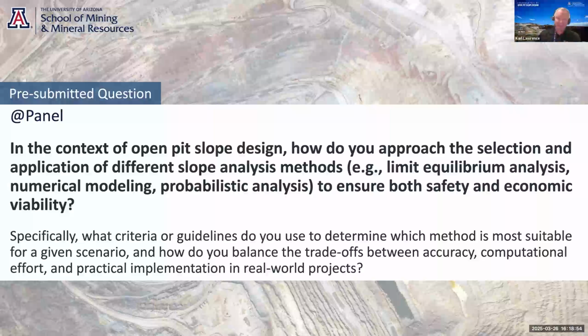The last part of that question just mentions practical implementation in the real world. And I think that's the part that stands out to me, because when somebody comes to us and asks us to run these different types of models, the first thing we ask is, well, how's your current slope performing? Because that's the best model you have. It's real life, and it's actually what you've been through. So whatever's happened on that slope, unless you're going into a different geology or geotechnical domain, you've largely lived through it. So that's what we would use to really choose the path forward. It's what you're seeing in the current slopes, what's typically governing in your area.